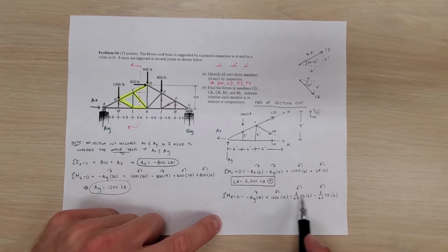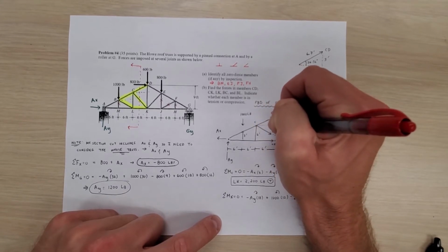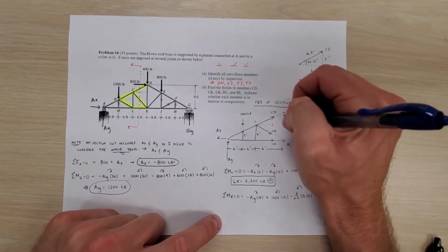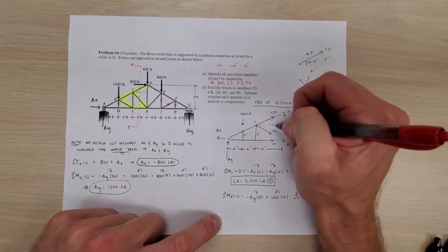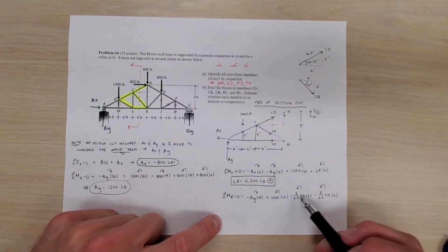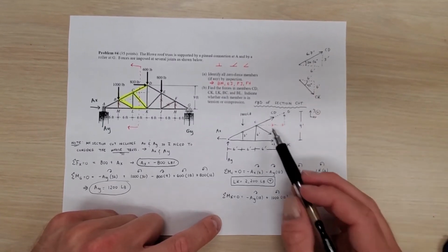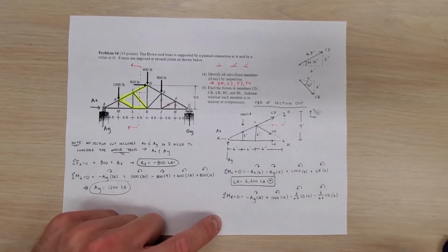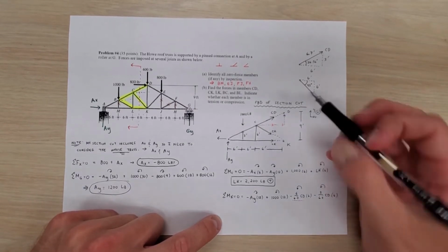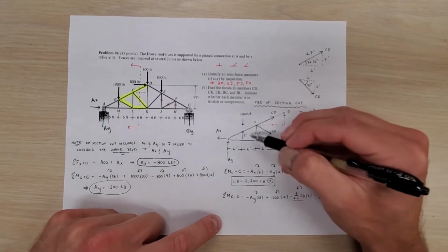And then we've got the two components of CD. So if you look at CD, CD is going to have an X component. And it's going to have a good old-fashioned Y component. And I probably should have drawn that arrow a little bit longer. Whoops! But I'll do that right now so you can see. So what we have is 6 over 6.7 CD, which is its X component based off of this similar triangle here. So we're taking the red component of CD right here, and we're multiplying that by 6 because it's 6 feet from there to here, and that's going to be clockwise.